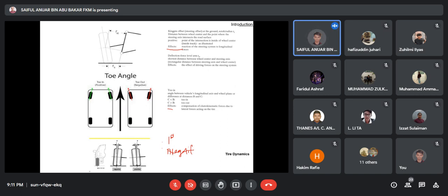So if you go to a service center to do your wheel alignment for the front, if you want to adjust your camber angle, it is usually within 1 degree, no more than that, because otherwise your wheels look like they are splayed open, what people call in Bahasa Malaysia terkengkang. Negative camber angle is just to increase the track width. In terms of performance, it is good.